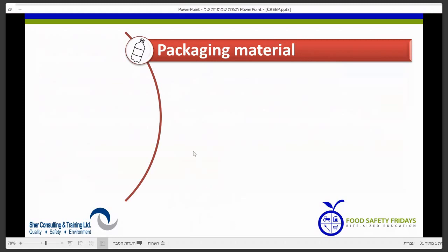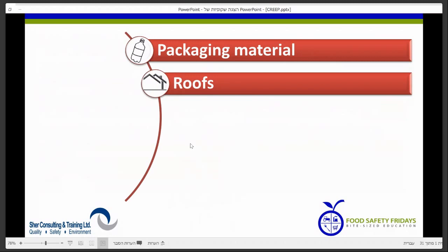Number 2, we have to think about the roof. This is really important in countries that have a dry season, but it's also important in other countries. The dry season is really important because during the dry season we have no rainfall, and during that time bird droppings accumulate on the roofs. And when the first rains start, usually in the beginning of fall, of autumn, then we'll have warm rain washing the roof and going towards our drains on the roof. And if they have been clogged because of falling leaves or pine needles, then we'll have accumulation of warm water with bird droppings dissolved in it, and we have a lot of Salmonella and Listeria on the roof.